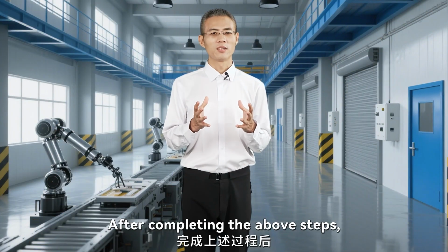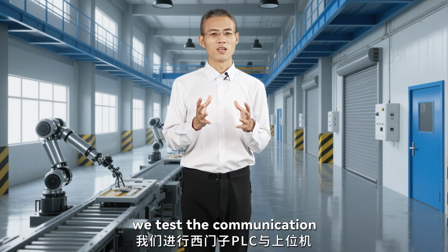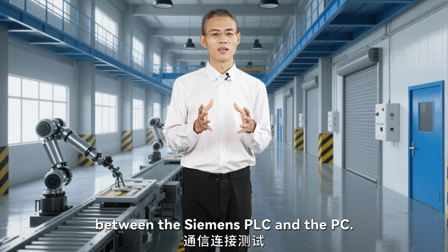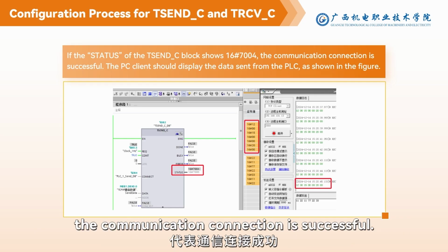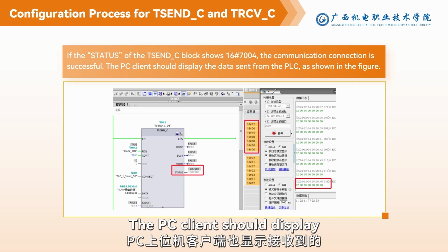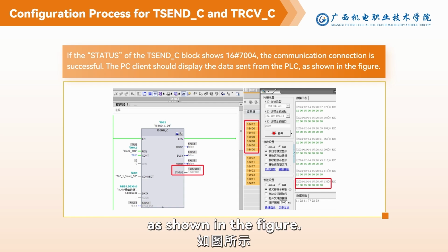After completing the above steps, we test the communication between the Siemens PLC and the PC. If the status of the TSEND block shows 16#7004, the communication connection is successful. The PC client should display the data sent from the PLC, as shown in the figure.